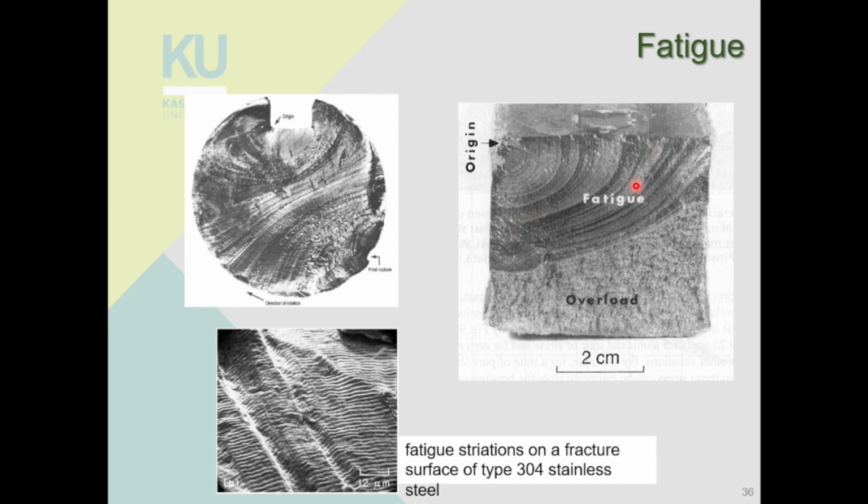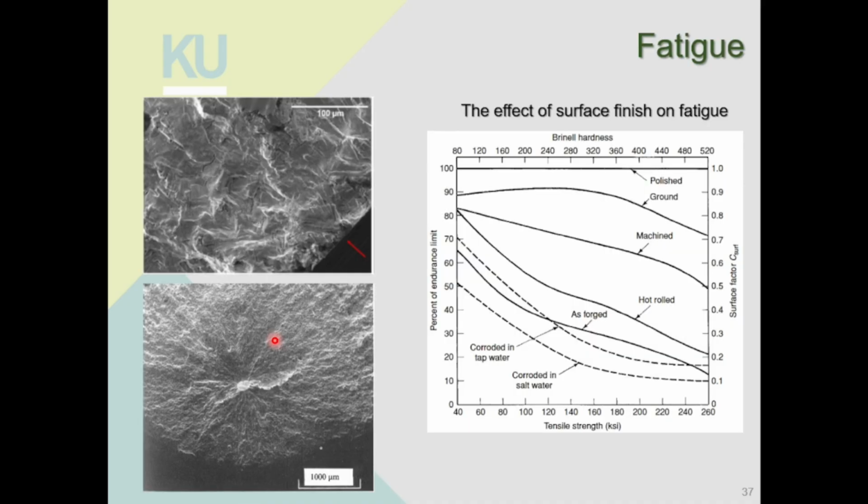And if you zoom in on the fatigue crack propagation area here, you can see fatigue striations. You can see lines where the crack grows by each individual application of stress, right? So this is one step that the crack can grow, each step that the crack grows.